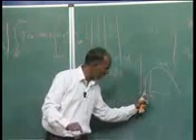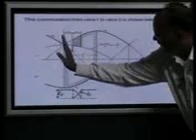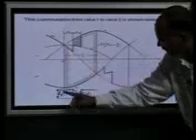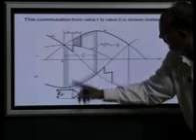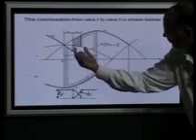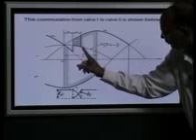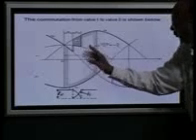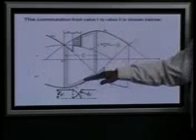Now we are just delaying by alpha degrees. As I said, it was 0 here, but I delayed it, meaning ID continues in valve 1, and then the current shares from 1 to 3 during this u period, and then 1 is off and 3 continues to conduct. This is the upper voltage and this is the lower voltage I was talking about.